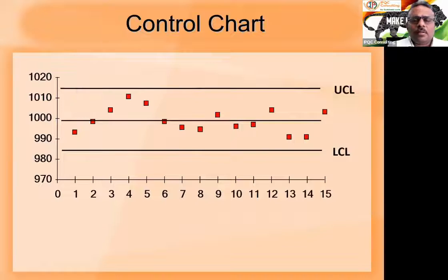And control charts, I said this, once you know the process parameters, you can calculate the upper control limit, lower control limit, and then the average mean you calculate and set this up. You start plotting the chart using the real-time data. Sometimes by seeing it, you can understand the process. Sometimes out of control may happen, so by seeing the trends, you can easily detect those things.